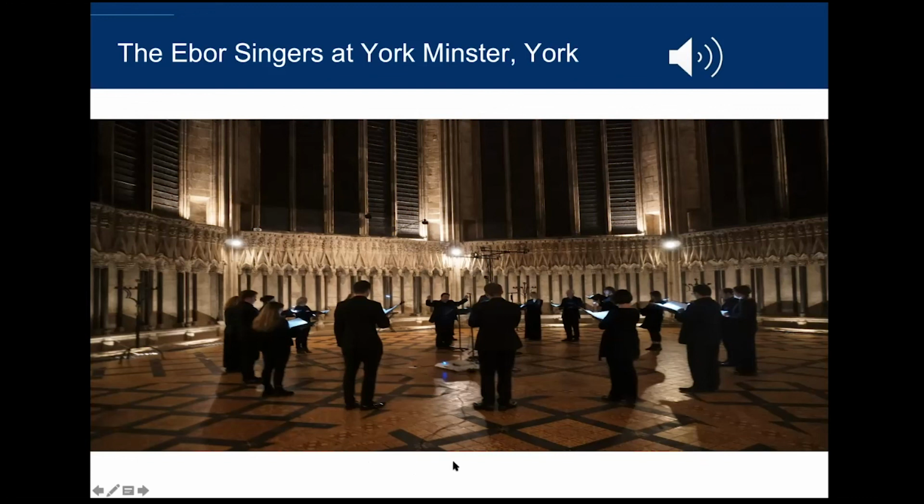But yeah, basically the reverb in this place is amazing. It's very large. I didn't measure it myself, but I think it's as long as 10 seconds. The tricky thing about recording in this kind of reverberant space is that if you place microphones too far, you may end up with very reverberant, unclear, unintelligible sound. But guess where the microphone was? It's in the middle, and each singer was about 4 meters away. 4 meters in this kind of space could be regarded as too far.